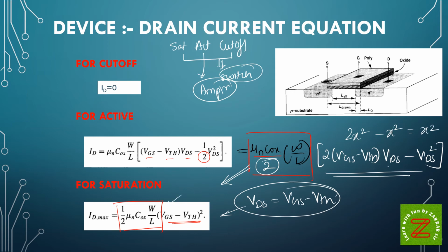So there are the 3 equations: ID equal to 0 for cutoff; for active it is mu n Cox upon 2 W by L, 2 times (VGS minus VTH) into VDS minus VDS square; for saturation it is mu n Cox upon 2 W by L (VGS minus VTH) the whole square. Now let's move further and understand a fantastic thing about MOSFET.